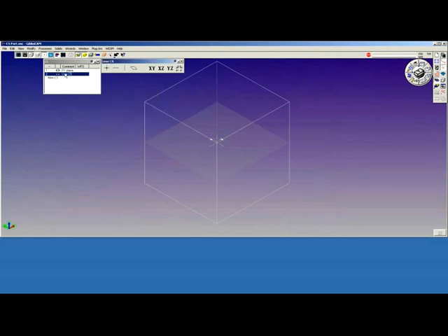I'm going to rename this coordinate system. I'm going to call it the top. The reason for calling it top is because it's going to be placed at the top of my 4-inch cuboid. Now to move it, I go to my coordinate system palette, third tile down on the right top level palette, and from here I activate the palette and I go to change origin.